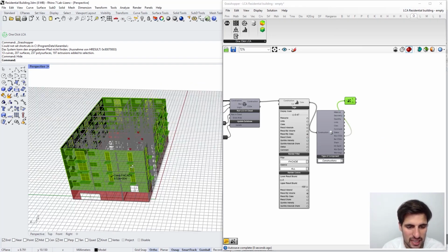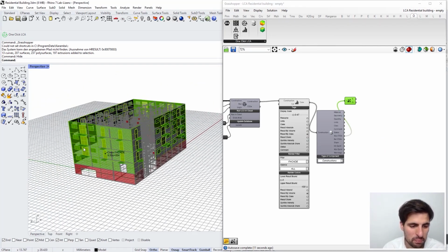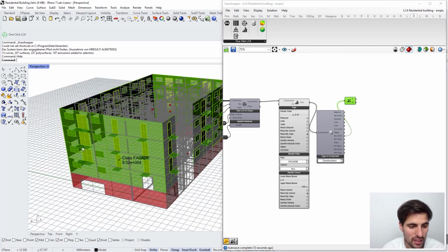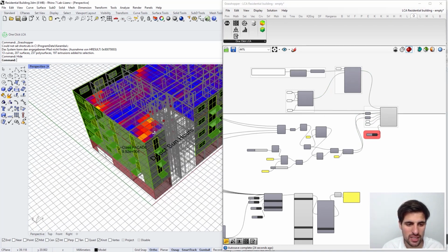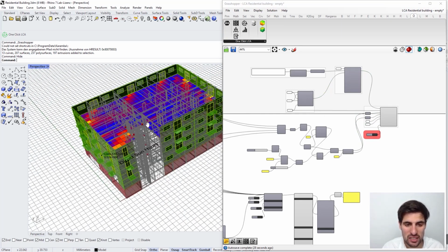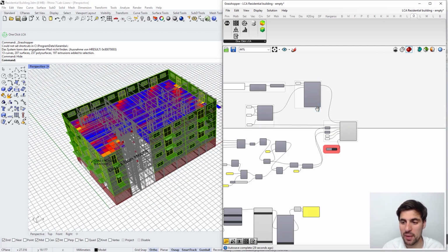And now the idea of this life cycle assessment is to parametrically modify the openings of the facades, right? Not just to see which influence it has in the overall life cycle assessment, as we can see in Grasshopper, of course, but also to combine the global warming potential that we are getting here with, for instance, this daylight simulation that we are doing with the Ladybug plugin, right?